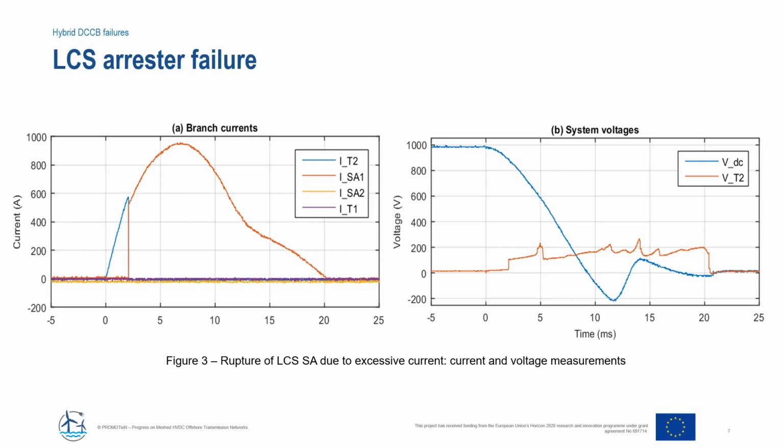The arc voltage can be seen on the right image, and two things are noticeable. Firstly, the voltage is fairly chaotic with multiple spikes and dips. Secondly, the voltage does not resemble the current waveform at all. In a resistive circuit, we would expect the voltage of the component to be proportional to the current at any point in time. In other words, we would expect the two waveforms to have the same shape, only scaled by a constant. In this case, however, the voltage seems to be even slightly inversely proportional to the current, increasing when the current decreases and vice versa.